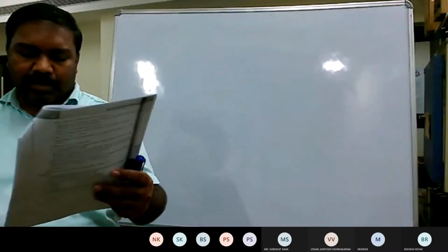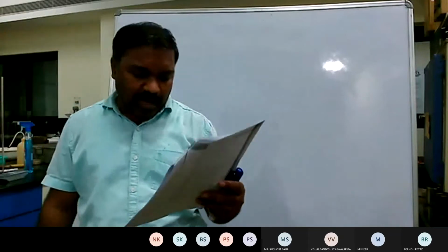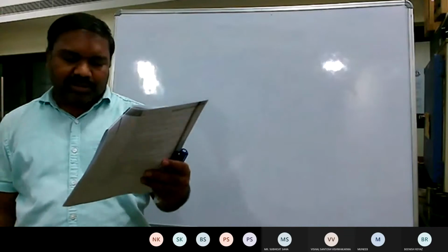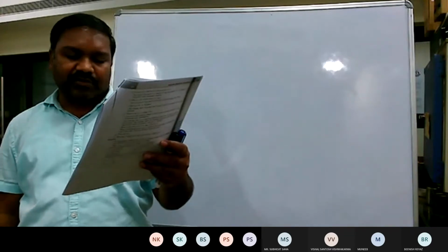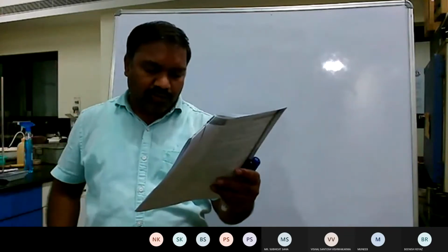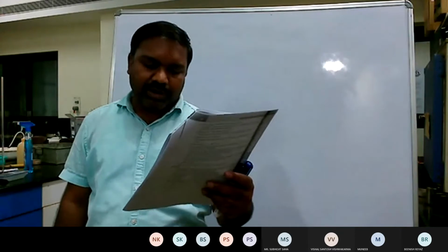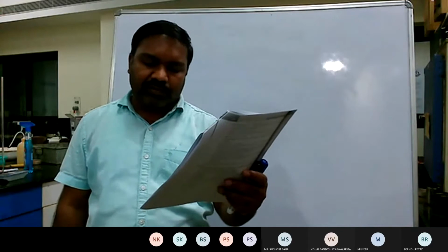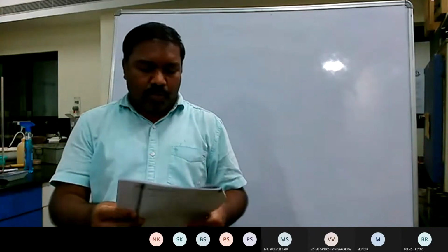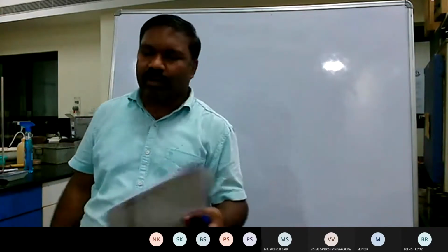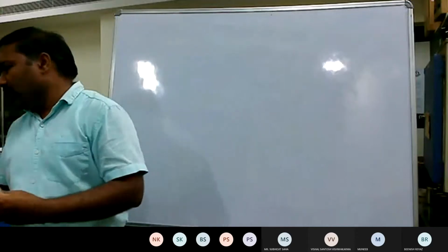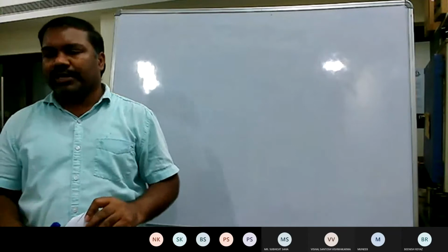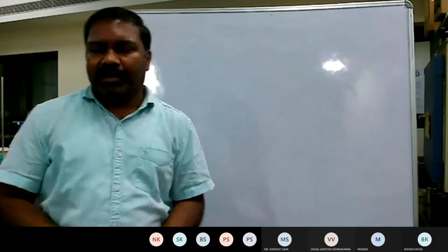A saturated clay sample was obtained from the field without allowing the water content and the void ratio to change. The sample was subjected to the following stresses in the field. Sigma is equal to 240 kilonewton per square meter, U is equal to 140 kilonewton per square meter, sigma dash is equal to 100 kilonewton per square meter. And here points A to H, so you have been asked to calculate what are the different stresses acting on it. Now first, let us try to understand what has been given in the sum.